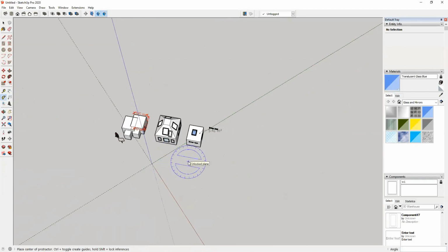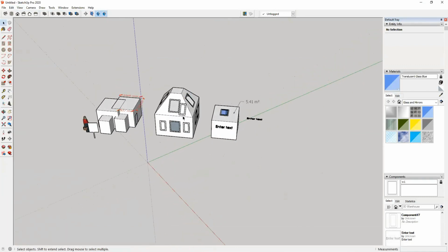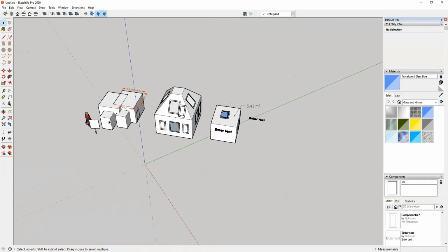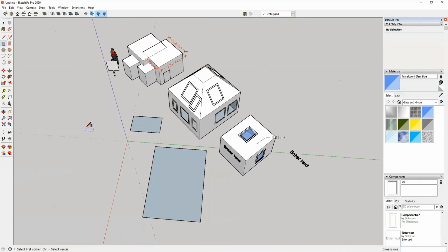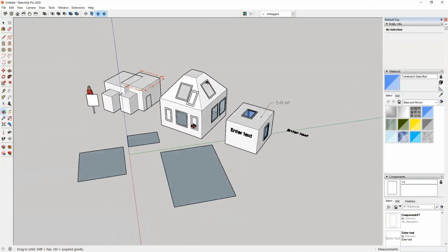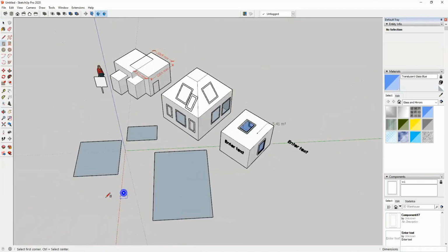Now you might be wondering, why do we want to change the axis? Let's clear the guides. That's because we don't always work at an angle of, let's say, 90 degrees. We sometimes need to create rectangles at these kinds of angles. If you try to create rectangles on the other axis, it might be very irritating every time you want to create a rectangle or lines.